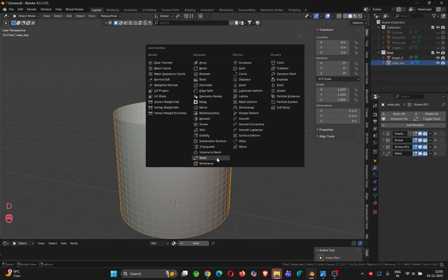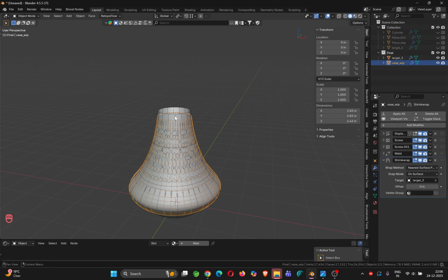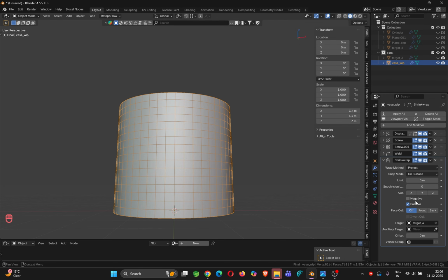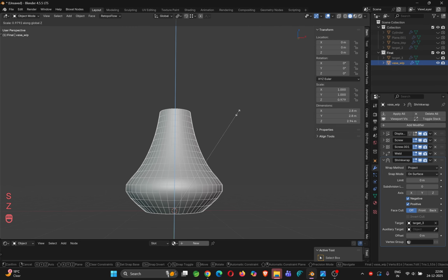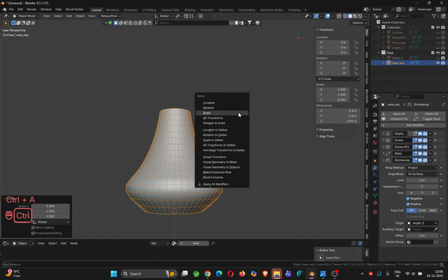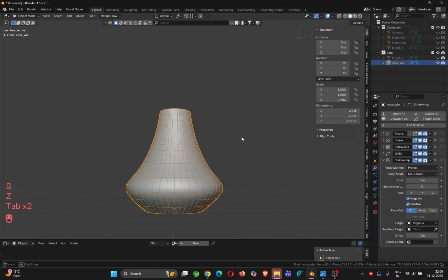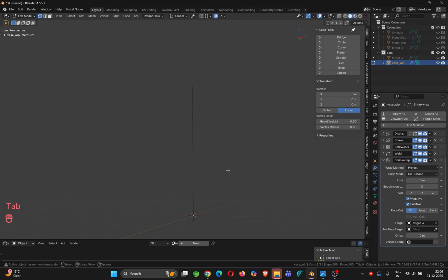So now at this point, what you can do is use the shrink wrap on this base model. Okay, now I don't need to see it. What you can do is project on the negative axis, and here, my friend, scale it on Z a little bit, a little bit. Okay, let me apply the scale. Okay, I will apply the scale later because it is causing some problem.